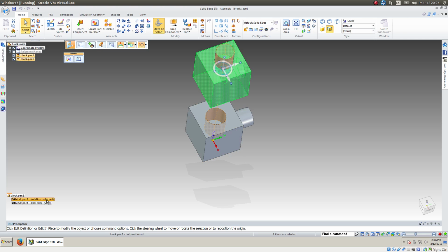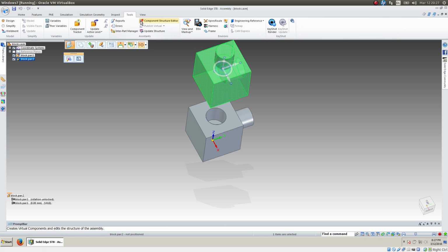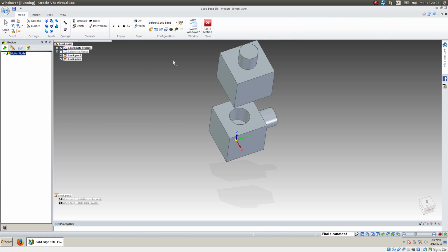The second one has an axial align constraint and then a planar align constraint. So it's allowed to translate in the direction of this axis for that hole. So this acts like a prismatic joint. And now we'll demonstrate functions using this assembly.